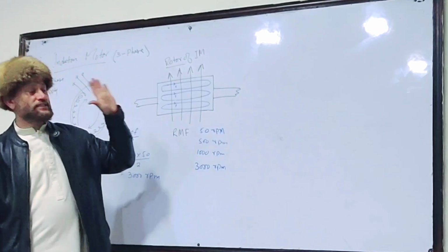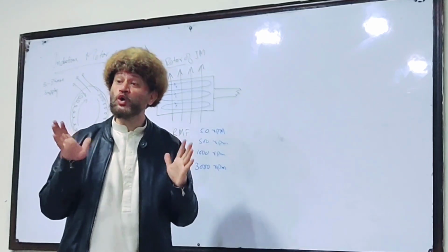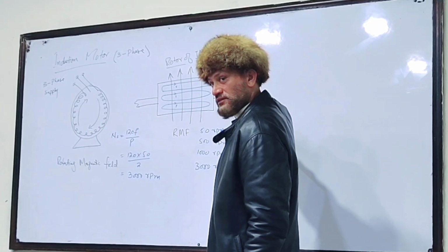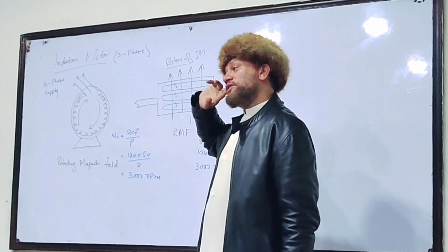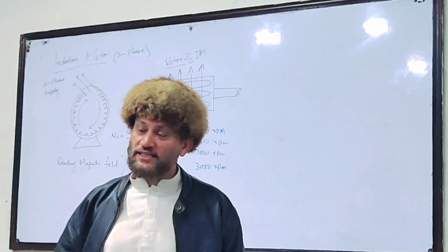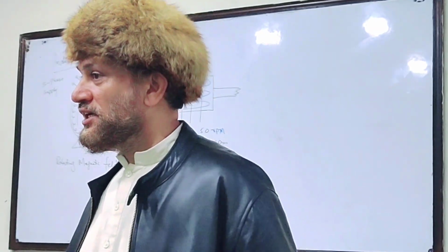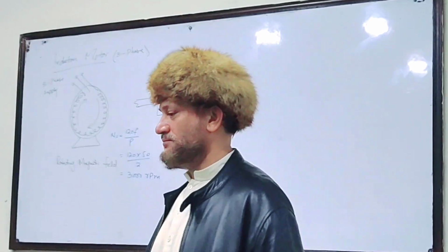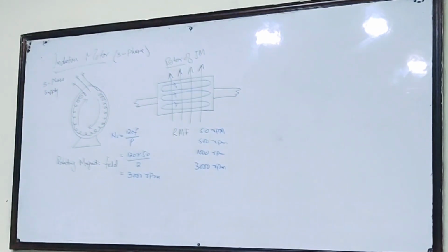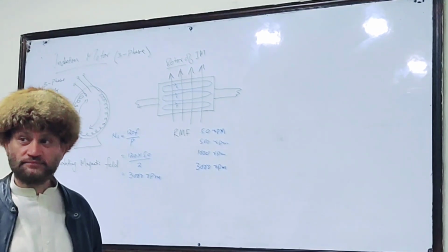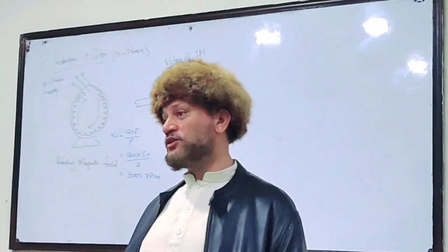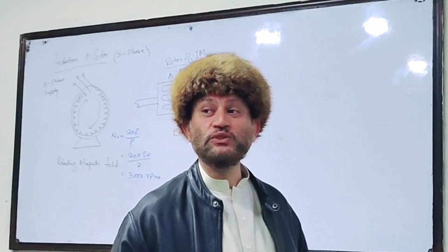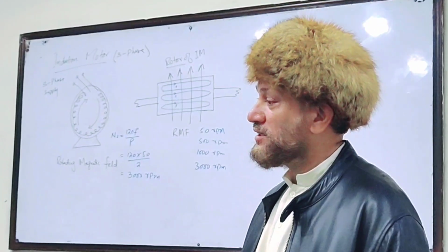Understand my point? Now, this scenario was on no load. There is no load on this shaft. So keep in mind that in an induction motor, a rotor cannot reach the speed of the rotating magnetic field. Why? Because whenever the rotor reaches the speed of the rotating magnetic field, there will be no EMF induced in the rotor bars.